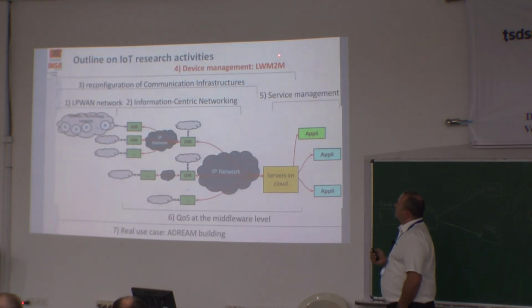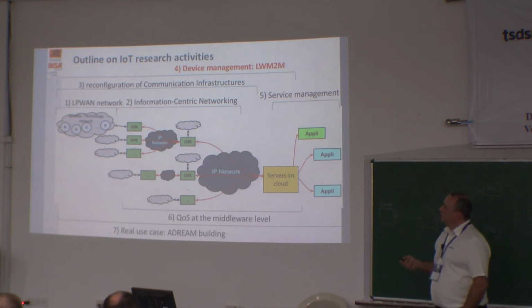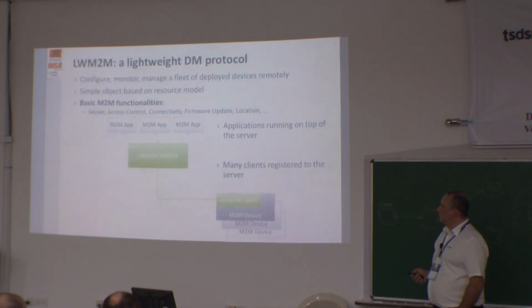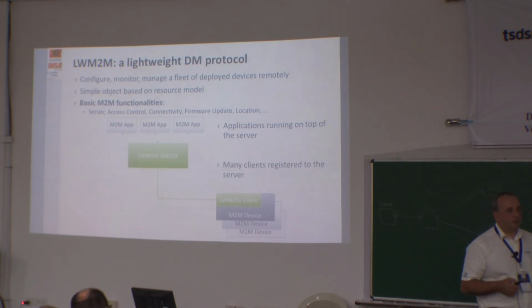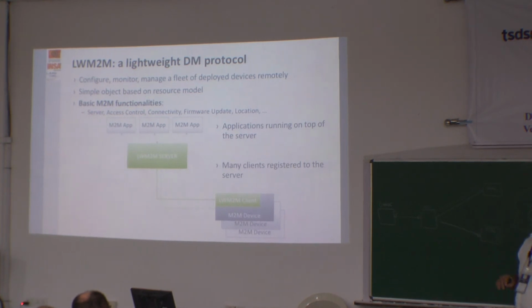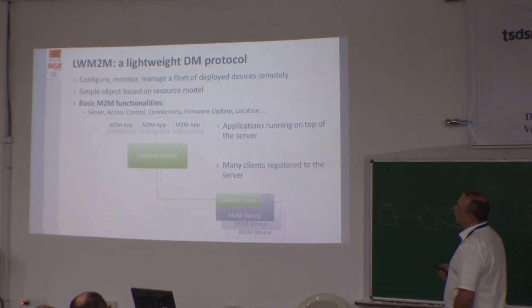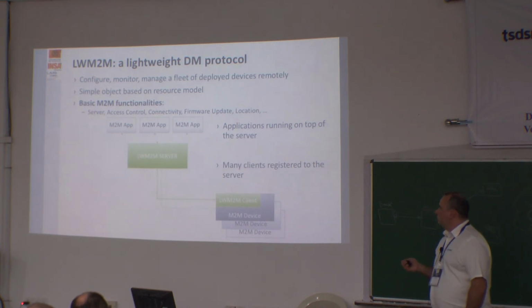We also work at the level of device management to help manage the deployment of services. To do that, we have made a connection with the lightweight M2M protocol. It's a dedicated protocol that can manage devices. With this protocol, you can make an update of firmware, deploy or reconfigure software, modify some parameters. We have done a connection with oneM2M.